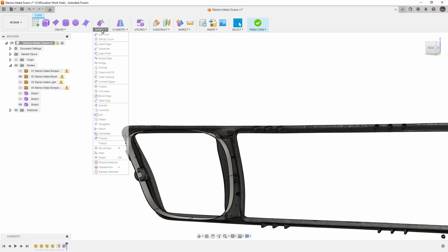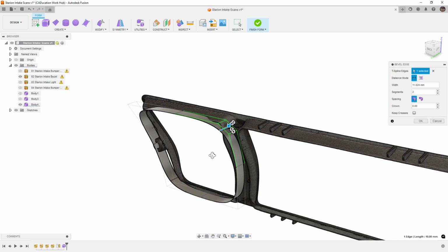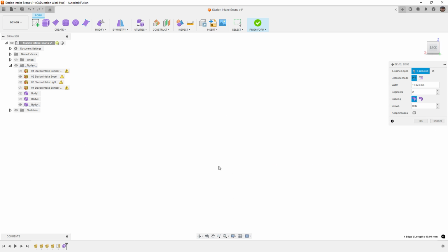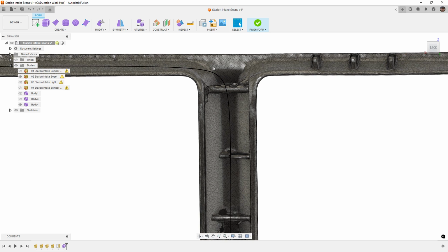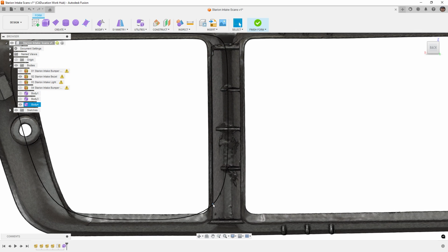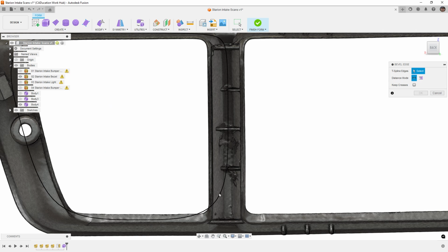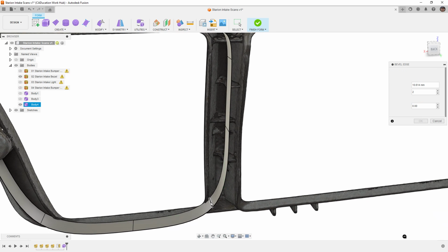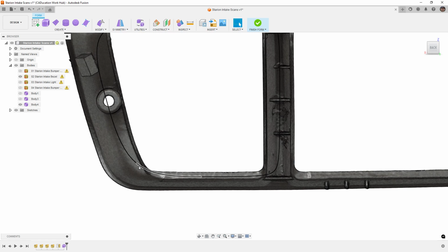So what this tells me is that if I use tools like bevel, for example, and I take this edge here, what this is going to allow me to do is, oh, I don't know why it disappeared like that. What this is going to allow me to do is use tools like increasing the crown and inserting edges to pull that edge back up and have it be closer to the box display edge. So I'm going to do that again. We'll bevel. I'm going to pick this one down here. And we'll once again increase the crown. And then we'll say, okay, pulling that down closer.